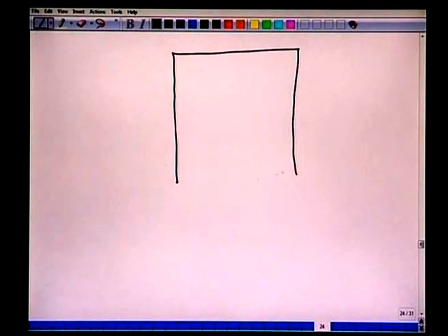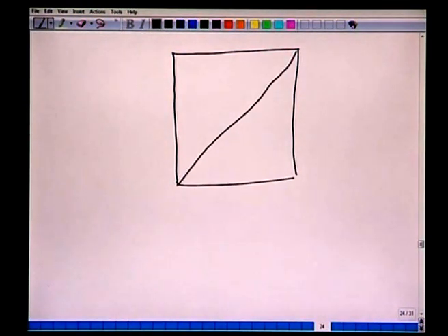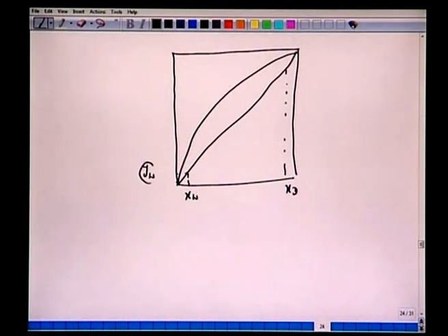Which means we can now construct this operating line for the stripping section without finding this negative intercept. Similar to the previous case, where we said that either we take a slope and the intercept, or we start from this xD and connect with the intercept, one can do the same thing here. This xW, with yW equal to it, also satisfies this operating line as well as this 45-degree line.